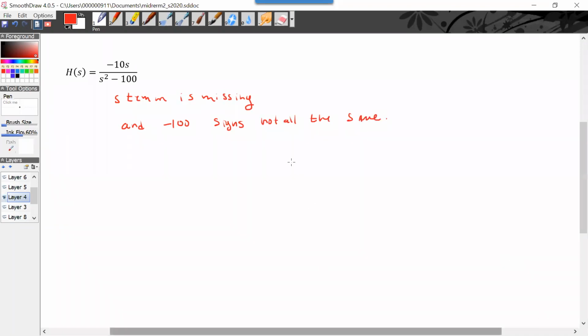So, what does that all lead to? Poles on the right-hand side, which leads to e to the plus t, all right? Now, if it's right on zero, if you could have purely complex poles, then you're going to get an oscillation.